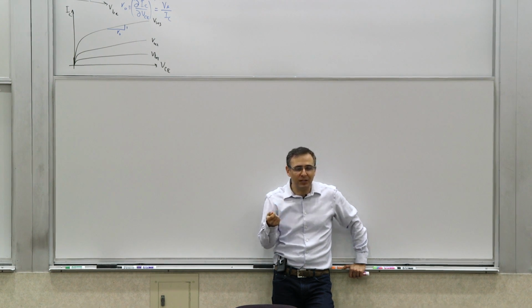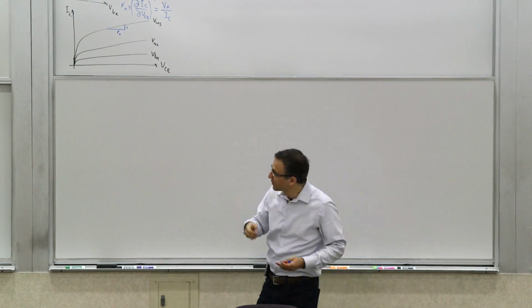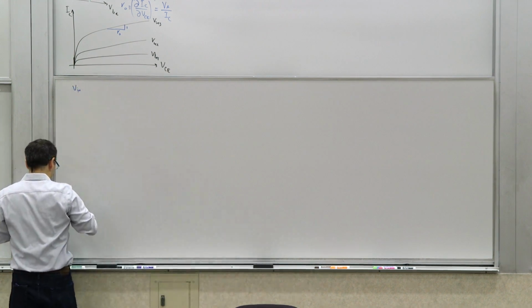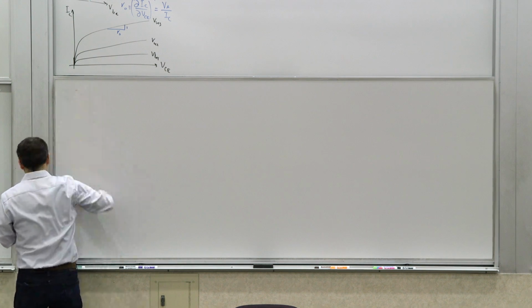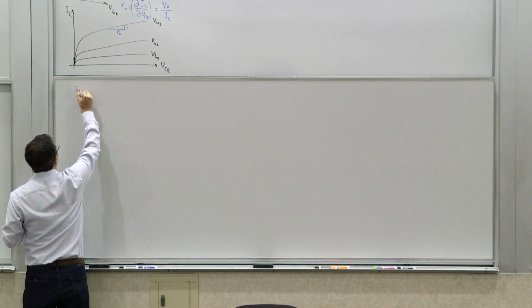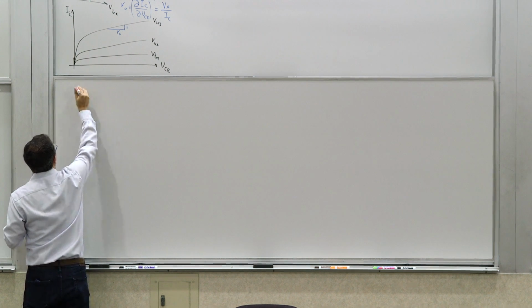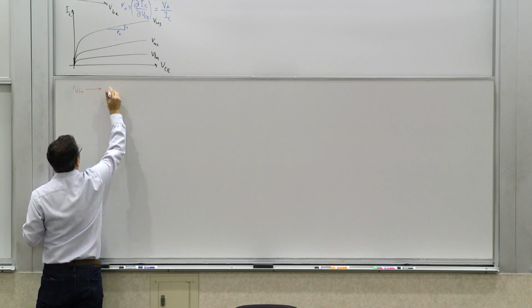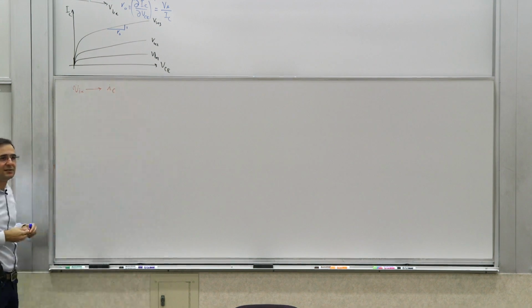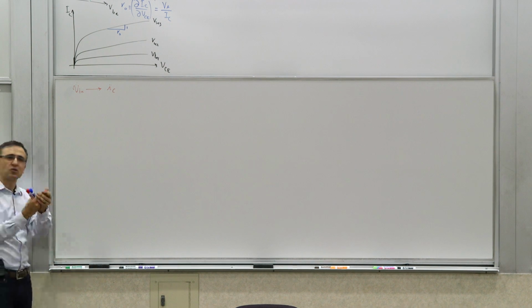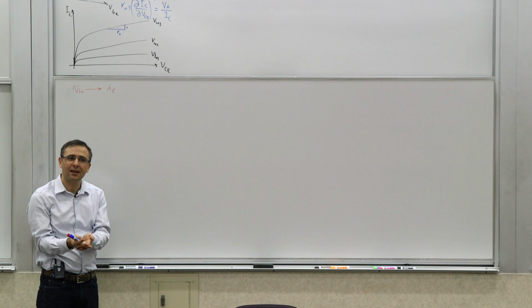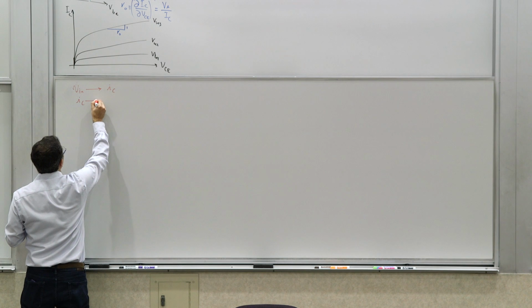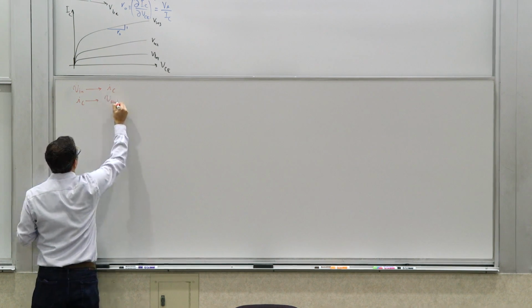So what else do we need? We have voltage fluctuations, let's say v_in, lowercase, converted to some fluctuations in the current, in this case the collector current, I_C. Now we want to convert a fluctuation in the current to a voltage again, right? So from these fluctuations in the current to some voltage, which is our output voltage.